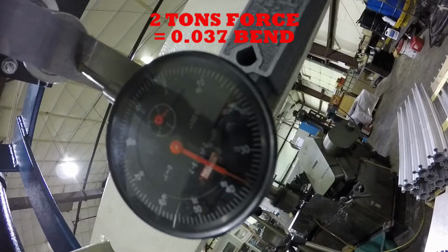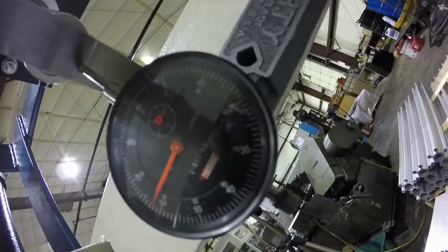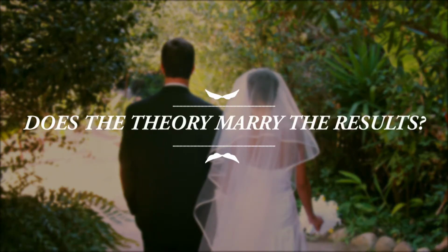Here you can see that 2 tons force equals approximately 37 thousandths of an inch bend. At this point, we were given the press about everything that it could handle, and that was approximately 2.5 tons force, and we got approximately 64 thousandths of an inch bend. This concludes the experimental phase.